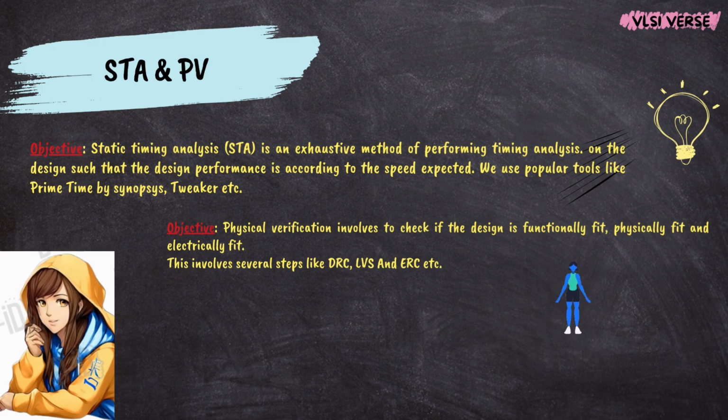Finally, we arrive at the sign-off stage. This is the final set of checks before the design is sent for manufacturing. Sign-off involves running a final DRC, LVS, timing verification, and power analysis to ensure the design is completely error-free and ready for fabrication. Once everything checks out, the design is considered tape-out ready, meaning it's ready to be sent to the foundry for manufacturing. And that's a wrap on the ASIC design flow, focusing on the physical design stages.